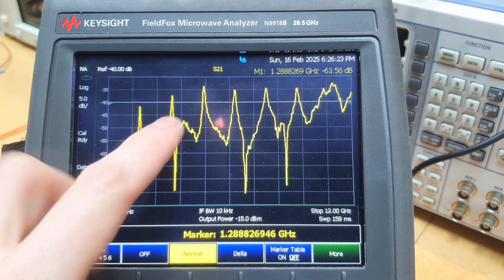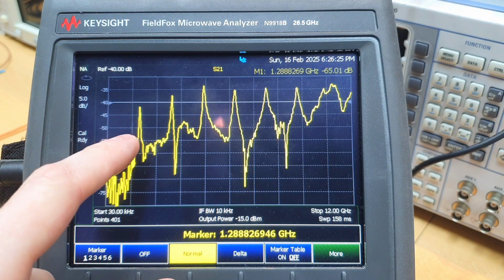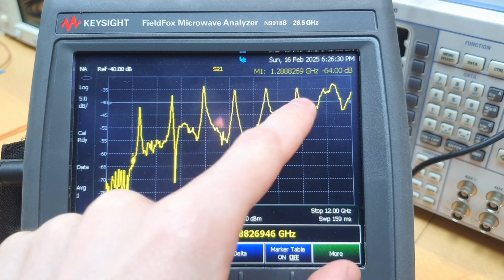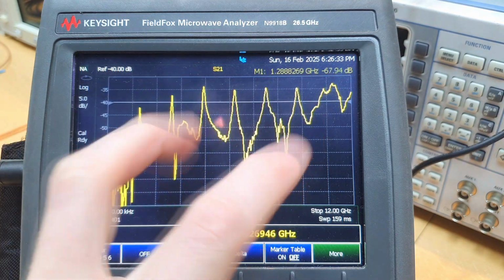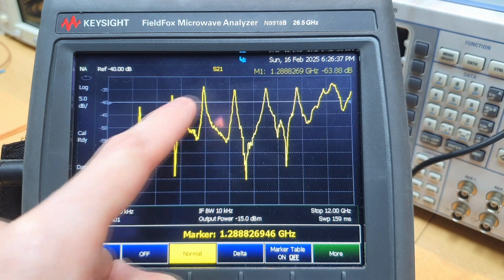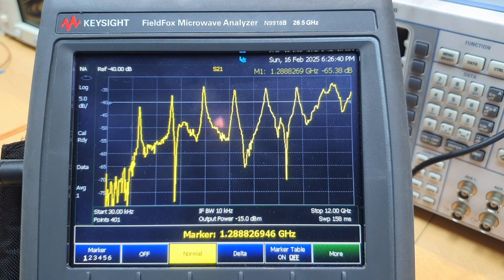What is fascinating about using a ring resonator is that we can actually measure the dielectric constant at different frequencies. We have an automatic sweep of the measurement, right? We can back calculate it here, back calculate it here, back calculate it at all the resonant frequencies of the ring.